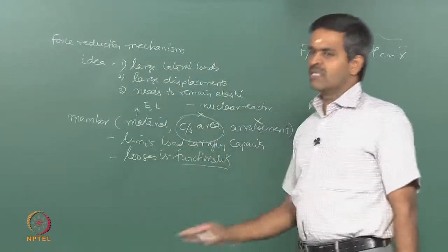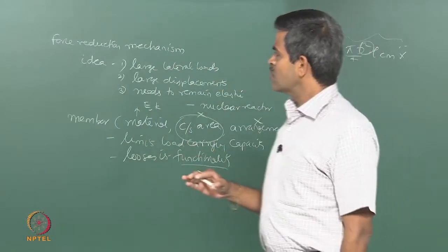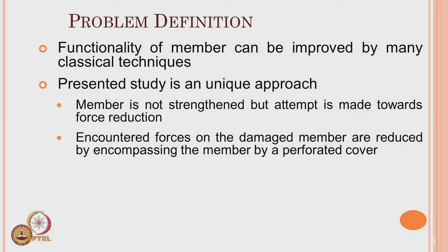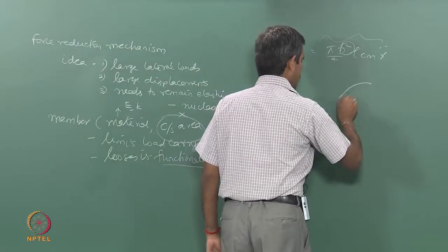The member is not strengthened in this case, but the attempt is made towards force reduction. Okay? The encountered forces on the damaged member are reduced by encompassing the member with a perforated cover. So, let us look at the plan. I have an offshore structural member.